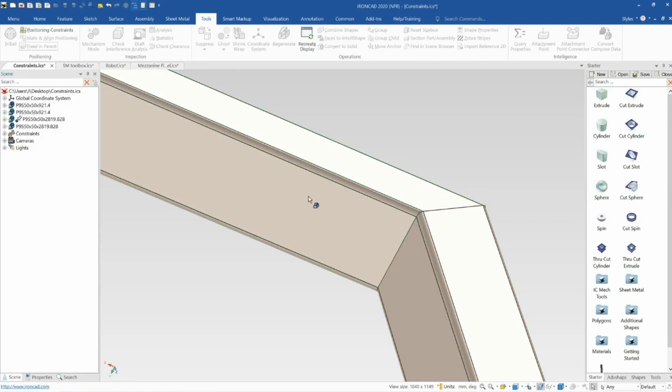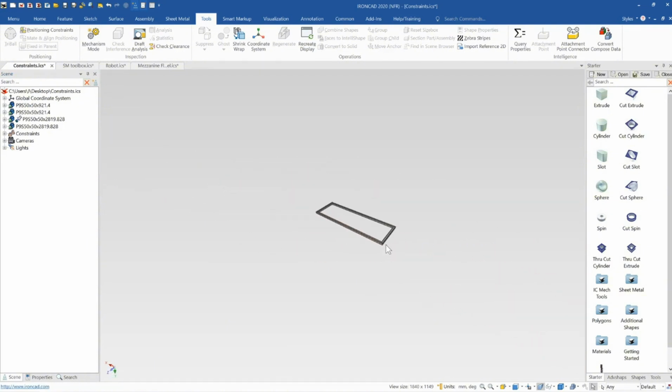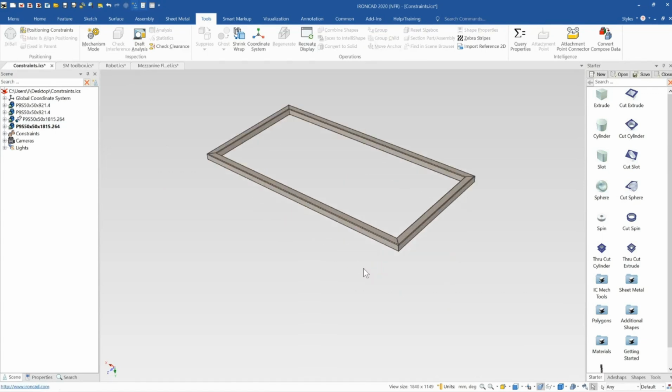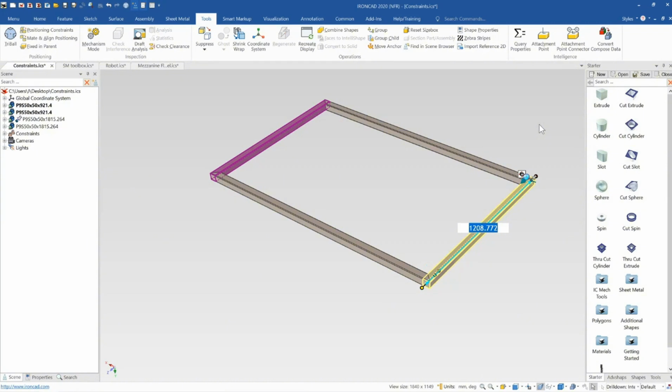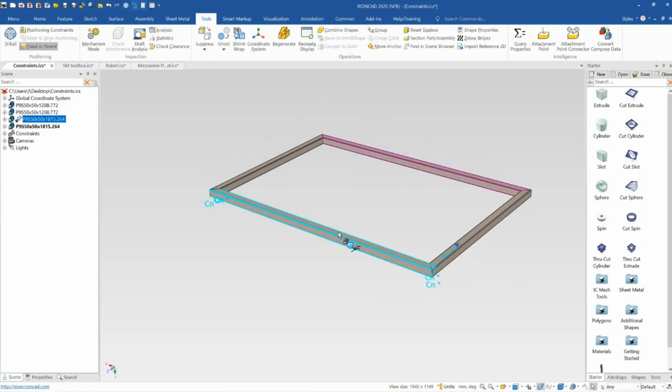Then I'll hit OK, and now we should have all of those constrained. And now if we size this, so we click down and we resize this model, you can see the frame is now following. Now we no longer need this one fixed in parent. You can see if we leave it fixed in parent, when we go to size in this direction, it'll actually move in that direction, because we've told the system that this one is actually locked. This is fixed on the earth, it can't move. So if we turn that off, now we'll be able to size in both directions.